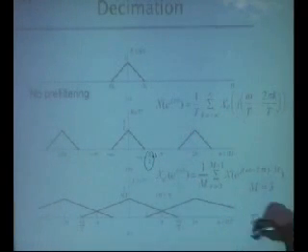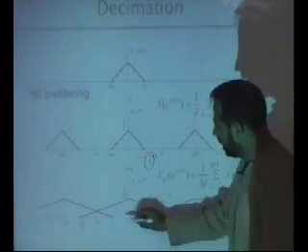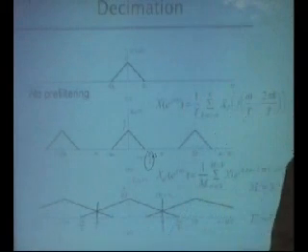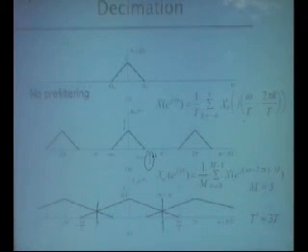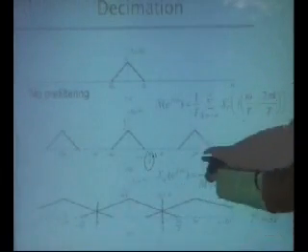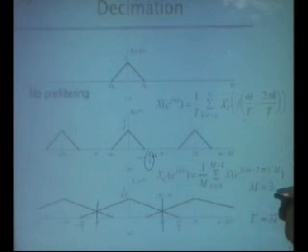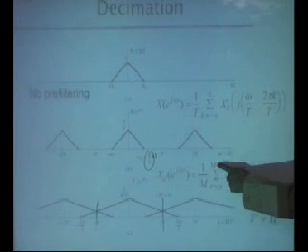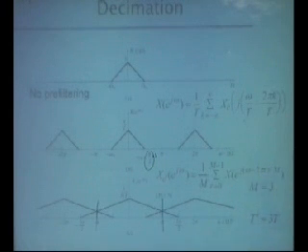And anything which goes above pi or below minus pi is very simple, it will come back as an alias. Because you are going to make a copy of this at 2 pi and minus 2 pi, this 2 pi will go to 6 pi, and you are going to have exactly 2 more copies of the spectrum, one at 2 pi and another at 4 pi.